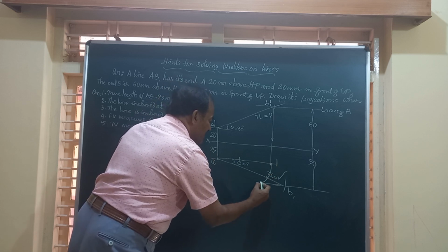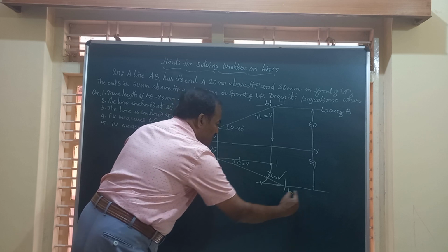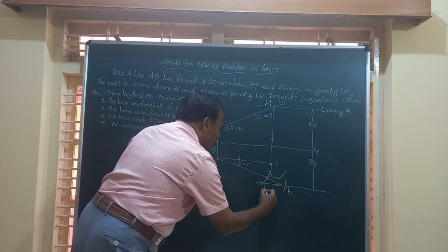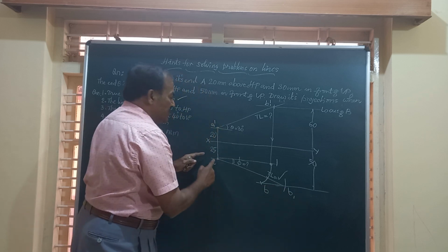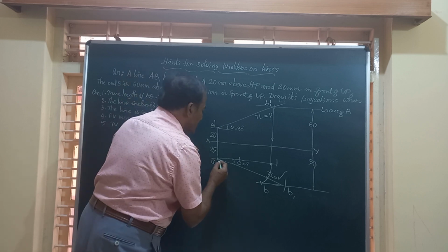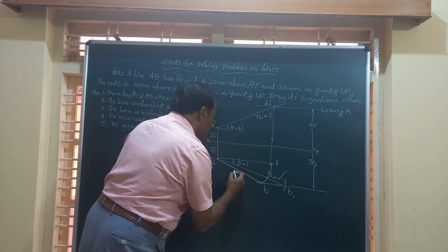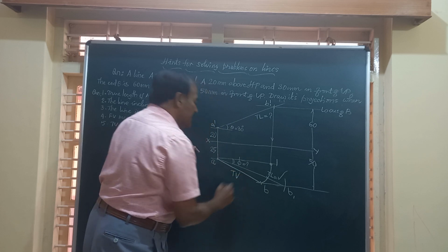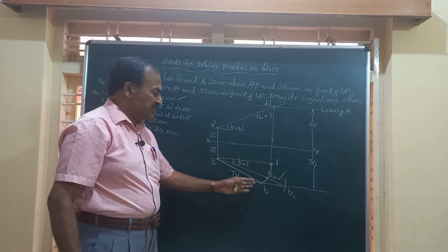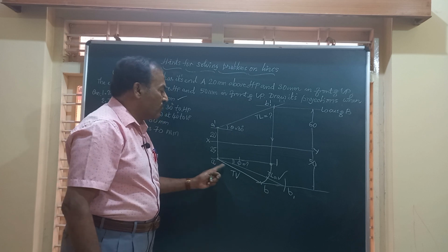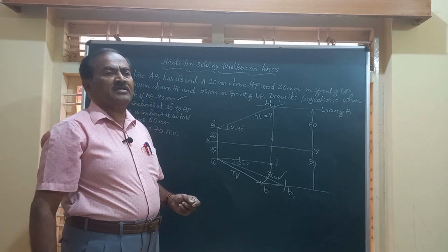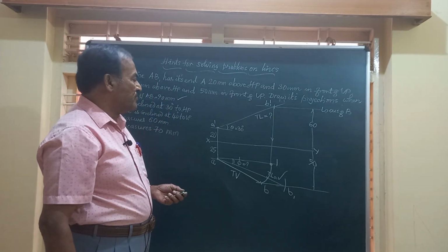And this arc intersects the locus of B at point B. So A you have got, B you have got. If you join A and B, friends, you get the top view of the line. So you can measure the angle made by the top view, and the measurement of that line AB.